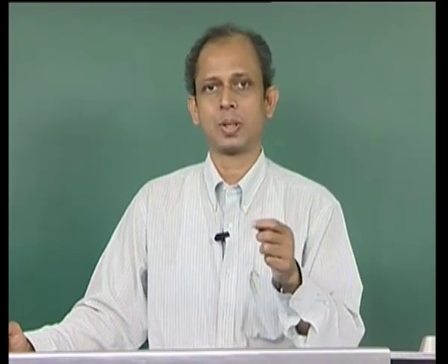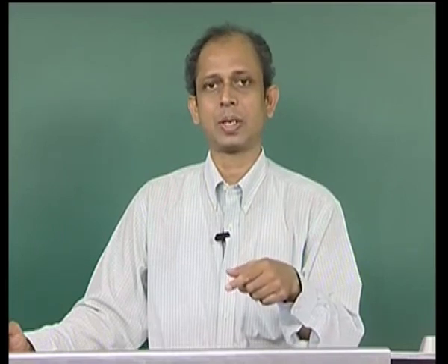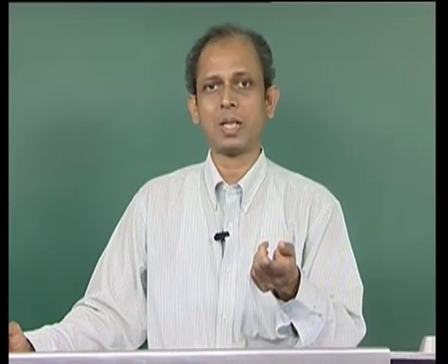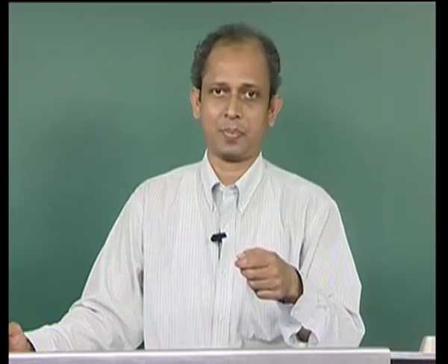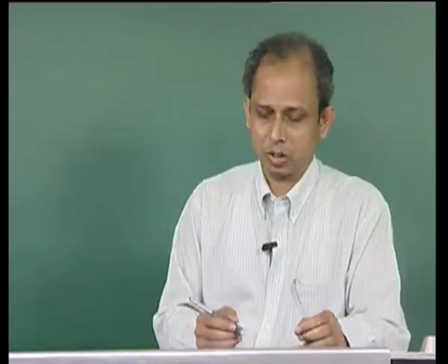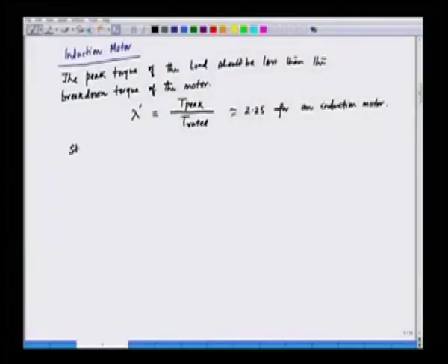So, after we have obtained this rated torque, we apply this condition, and the condition is that the peak torque by the rated torque should be less than lambda prime. So, we can note down the various steps. Step 1: select the rated torque based on T equivalent calculated.